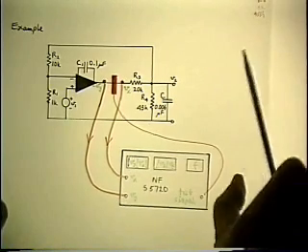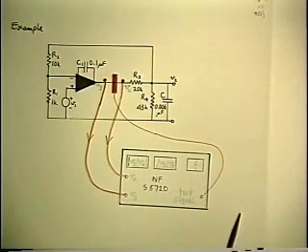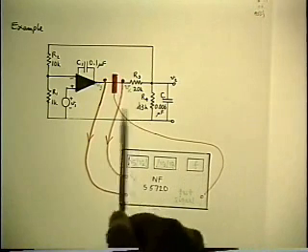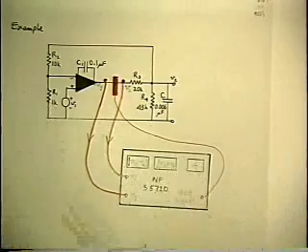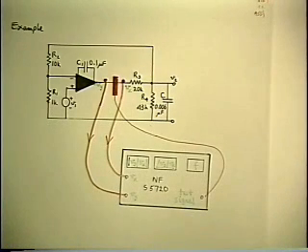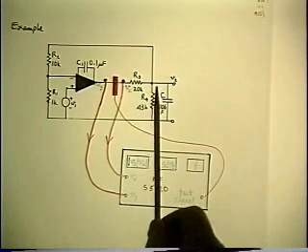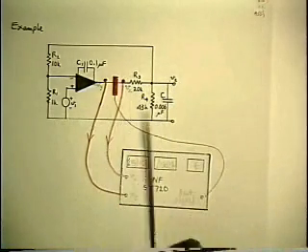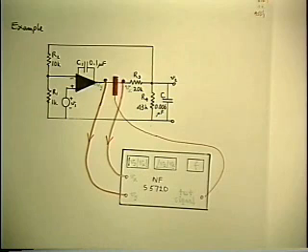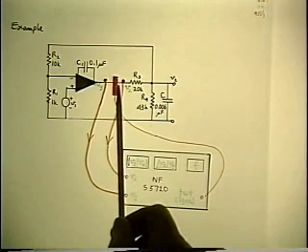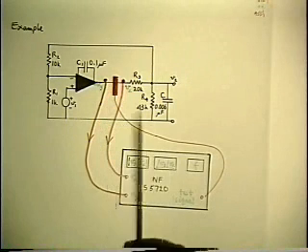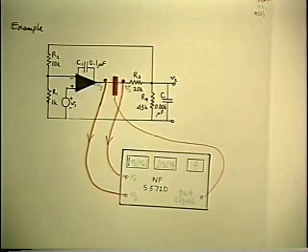And you're ready to go. And your control computer or your hand or whatever, you just go right along and do your frequency run. And you have not broken the loop. You don't have to fuss with applying a bias and adjusting it. And because of using a transformer to do the signal injection as well, you have nothing but 3 probes to hang on. And that's all it takes.